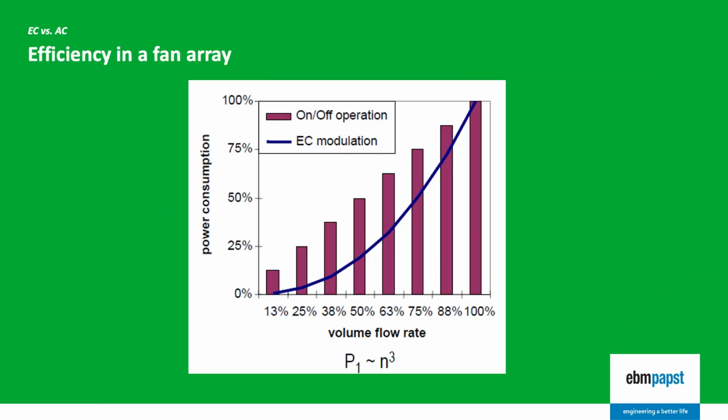The most significant advantage is that their efficiency level of up to 96% is substantially higher than the typical 70 to 80% achieved by AC induction motors. This equates to better utilization of electrical input power and reduces heat loss, which increases service life. The benefits in terms of efficiency are even more apparent in part load operation. The integrated electronics of an EC motor permits infinitely variable control, so the speed and thus the power is adapted to the equipment's requirements at any particular moment.